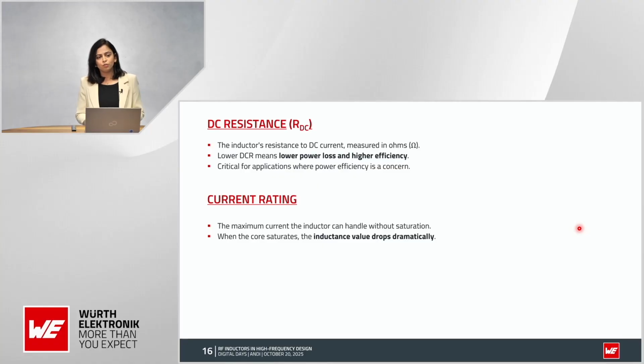Okay, and then we move towards the current rating. We might say that current rating is only for power inductors, but that is not the case. In RF design also, it's an important criterion. The maximum current an inductor can handle without saturation is called its current rating. When the core saturates, the inductance value drops dramatically.